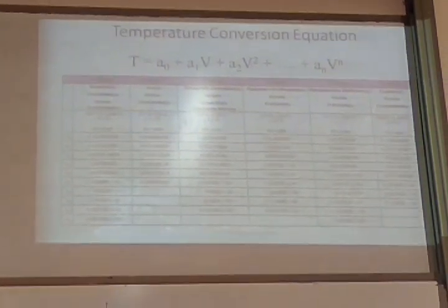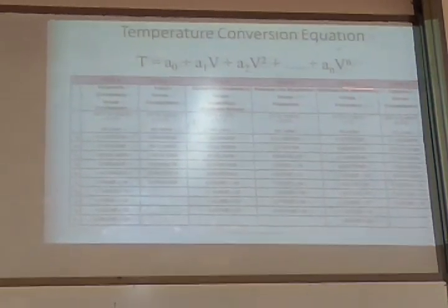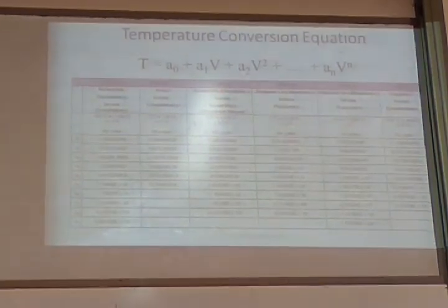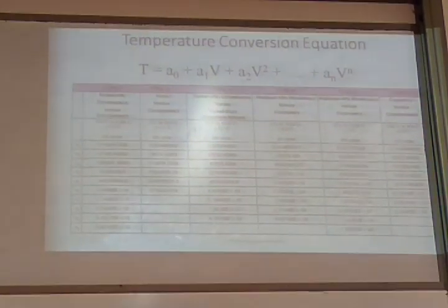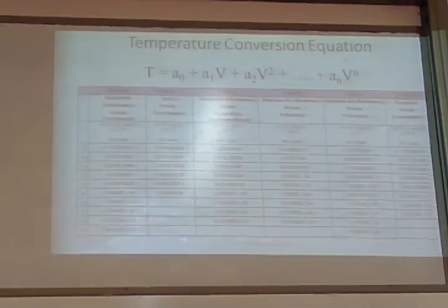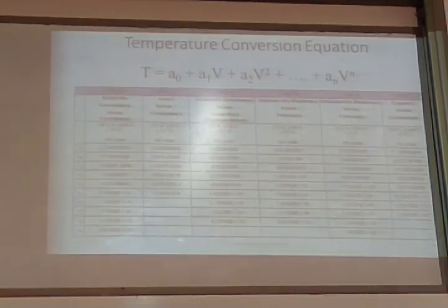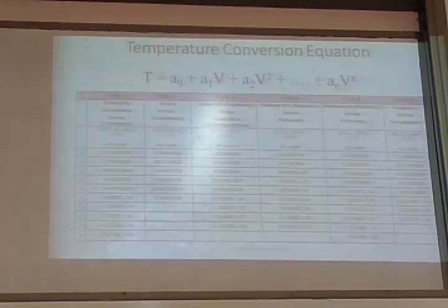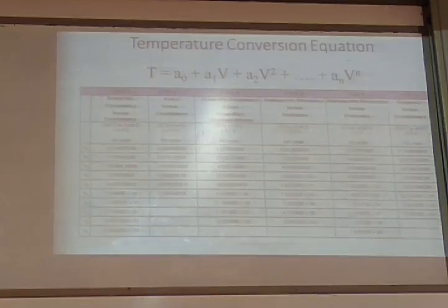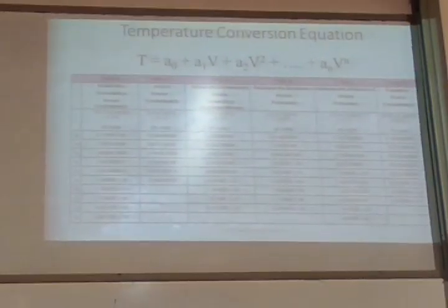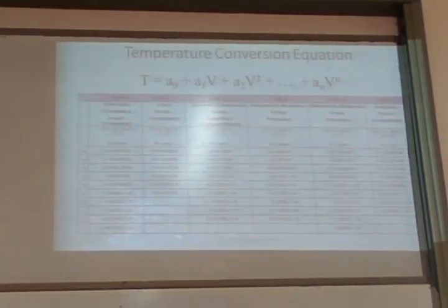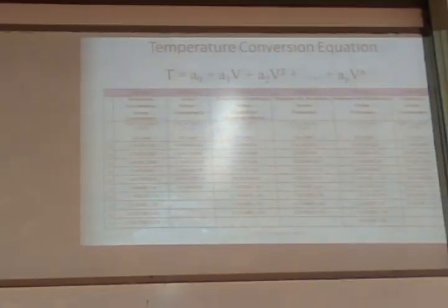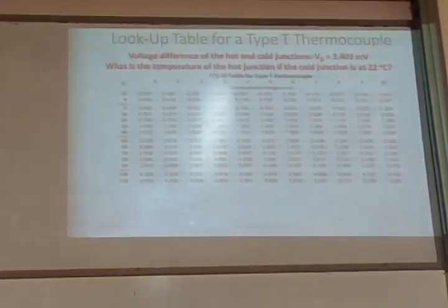That's why they have been given some technical commercial names, S type, R type. If you go to the shop and ask, sir, give me a nickel chromium, nickel thermocouple, that fellow will not understand. You simply say, give me a K type thermocouple, and he understands. So that's a commercial name, K type, S type, R type. It's a trade name, so people will understand.